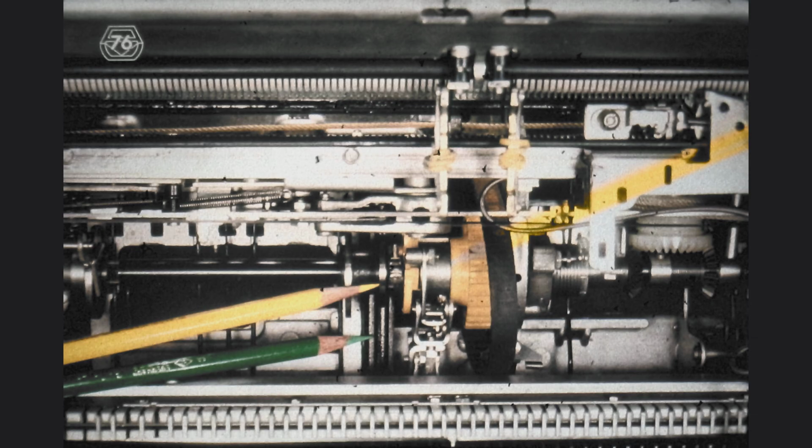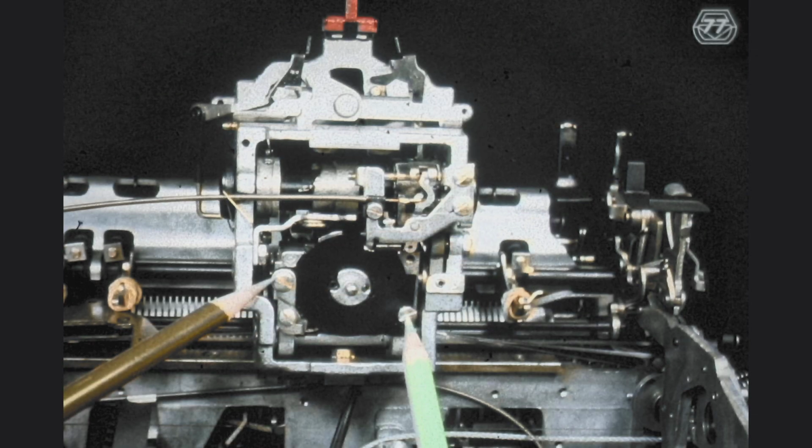When we studied the input section, or the keyboard, we learned that the -5 selector latch releases the spring tension of a negatively powered mechanism. Using the pulleys, the rotate tape, the levers, and the links we have just studied, the spring which causes the R5 cam follower to follow the cam is the rotate spring, located at the bottom of the rocker behind this black plate. By removing the screw indicated by the yellow pencil, loosening the screw indicated by the green pencil, and also loosening the screw below the green pencil, we can uncover the rotate spring, which we will do for you now.